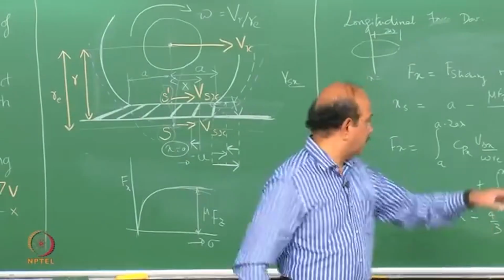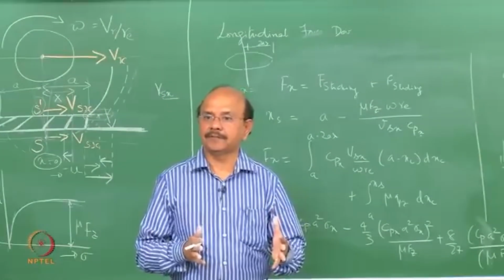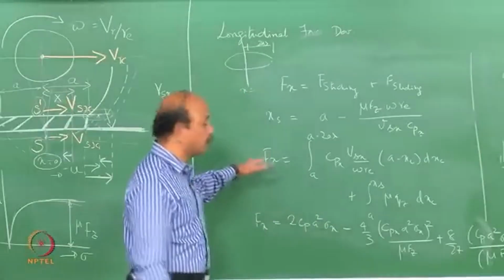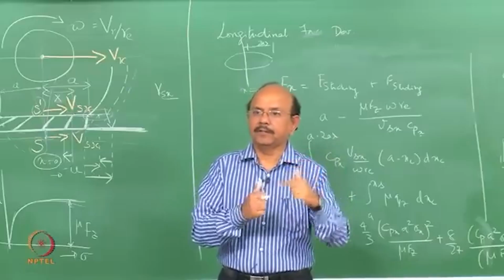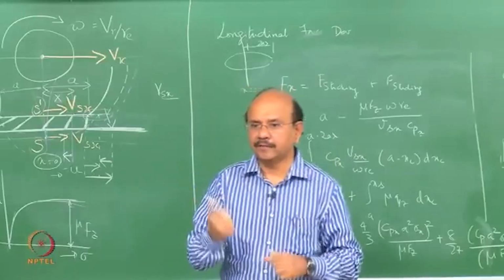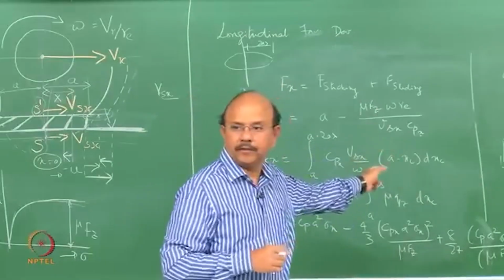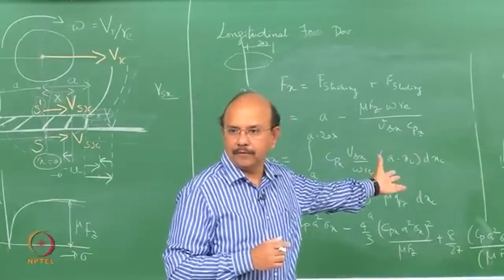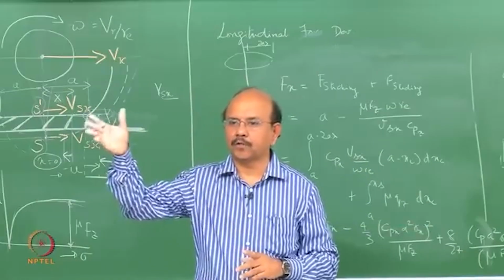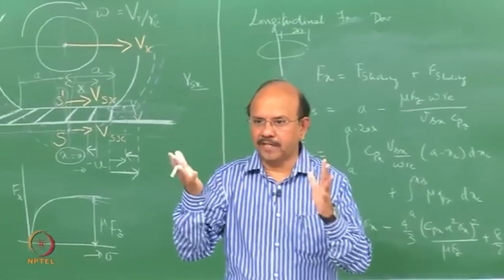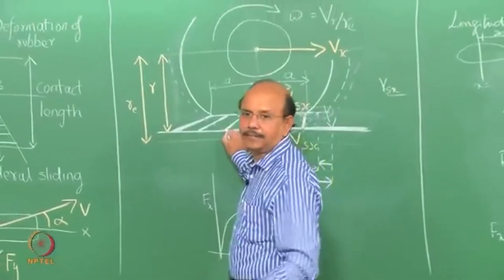When we equated Qz and Qx, that is possible when there is no slip, right? The condition under which the slip happens, where both of them are happening, is that the Qx, the force developed per unit length, is equal to mu into Qz, this multiplied by dx, that into Qz is what I had written down there. So that's per unit length. So mu into Qz is equal to the Qx developed. When both of them are the same, then that would be slip.